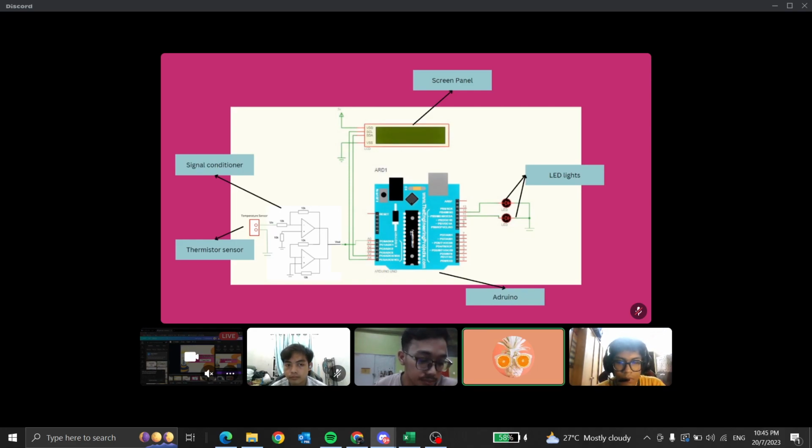The first op-amp will receive the signal from the sensor and pass it through its negative input pin. Then the output from the first op-amp will go to the negative input of the second op-amp, and the second op-amp will provide the final output. Using these two op-amps allows us to create an instrumentation system with high gain for accurate measurements. Additionally, as the signal passes through these op-amps, linearization will occur to ensure that the output of the sensor is directly proportional to our measurement value. Next.